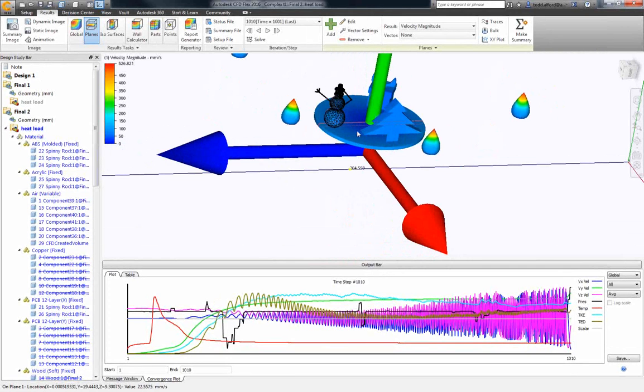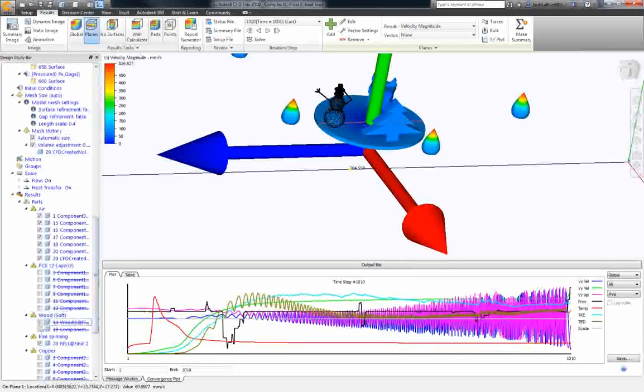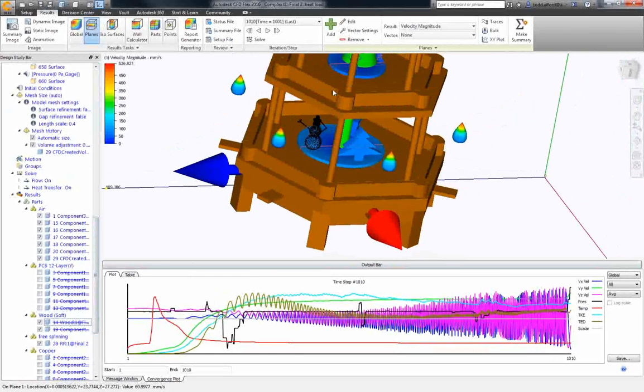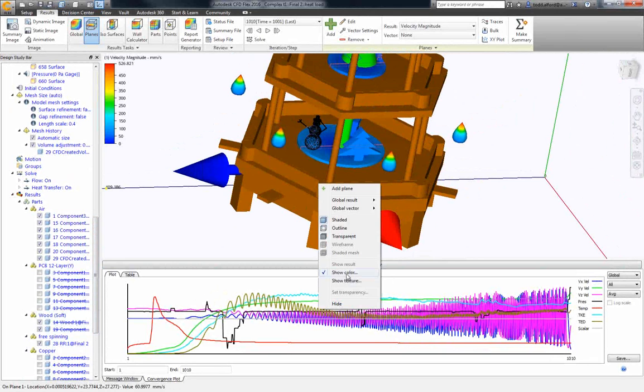And they're separate parts from the post itself, which was actually a very nerve-wracking thing for me to start with, because most of the time when you're doing a rotating region, you have an impeller or a single piece that we're really worried about. So I did mesh all of those. I could actually have them as not meshed. You could see before that I had a view saved where we were showing parts that are suppressed. I can do that by making them visual here, and then they're actually shown by color. So I can decide what color I want to show things.